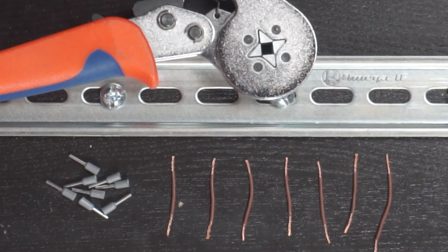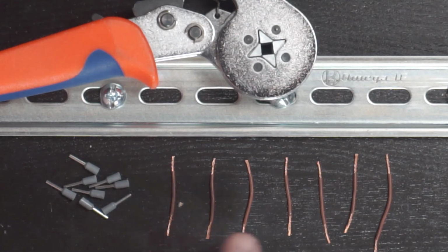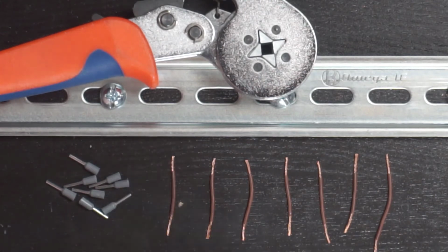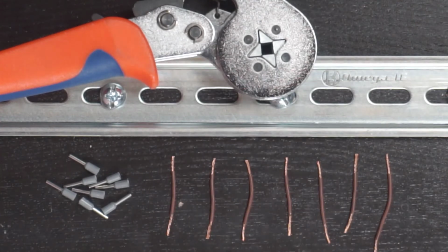All right, next we're going to talk about that jumper assembly that's going to run the 24 volts or V+ signal from all the relay commons to the next, and also to the V+ terminal for the high-speed output. So in preparation to make this little jumper assembly, I just cut 7 little segments of wire here. This is, I think, 20 or 22 gauge wire. I stripped off both ends here. You'll notice all these wires are a couple inches long, maybe 1.5 inches, 1.75 inches. And I've got one that's a little bit longer, just because that one has to stretch from the last relay common over to the high-speed output common.